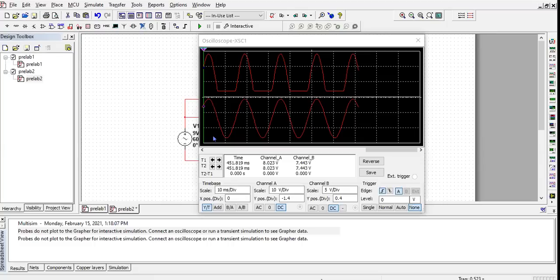Now if I want to read the values, although they are appearing here, if I want to read what is happening, how can I read? Obviously it will be peak to peak voltage. What I am going to read, these are the RMS values you can pick from here, right? Why are these almost the same? There is a difference of only 0.7. So input is 8 while the output is 7 because there is a drop of 0.7 across the diode.